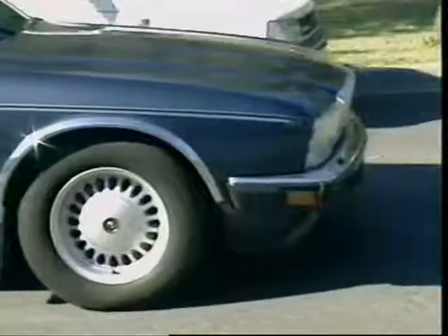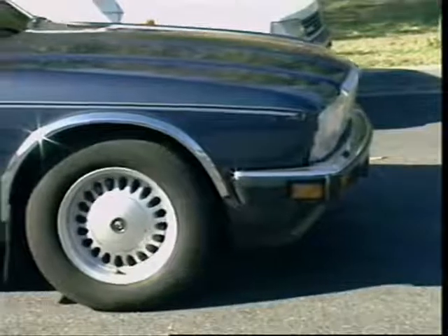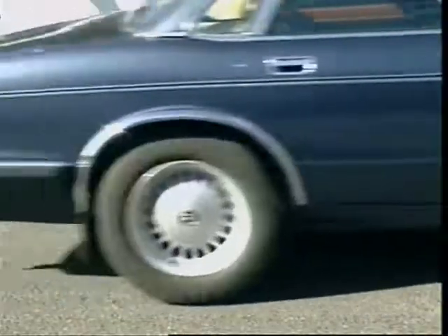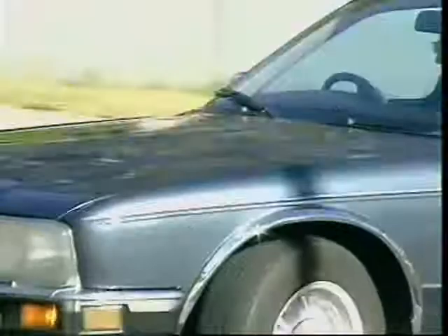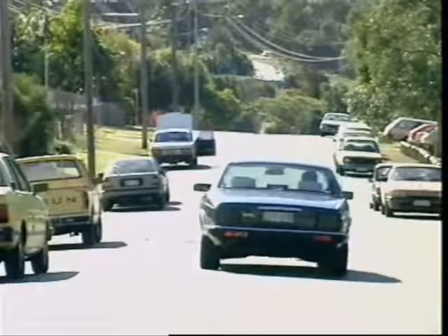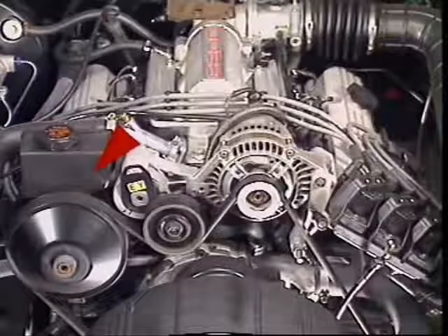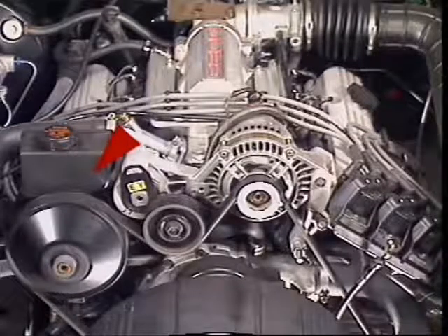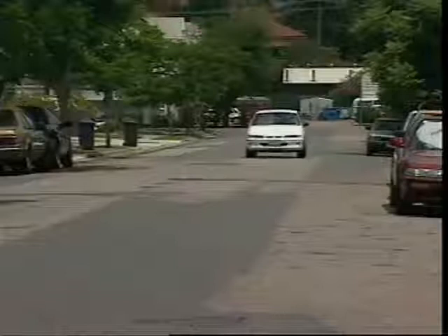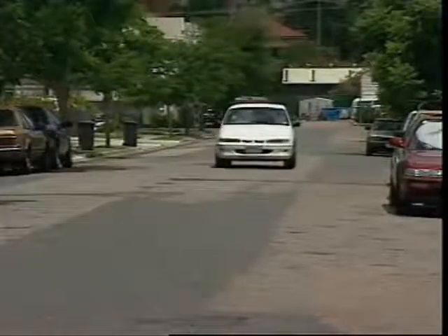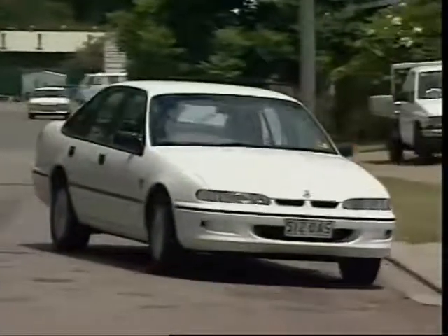With heavier vehicles, increased use of front-wheel drive and wider low-profile tyres, more steering effort is needed, so power assistance is used. A hydraulic pump is driven from the engine to provide pressure to help the driver. The power steering system is designed so that even if the engine or the power steering system fails, the vehicle can still be controlled. However, much more driver effort is required.